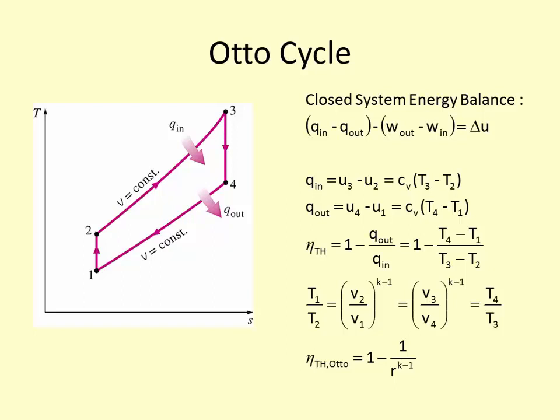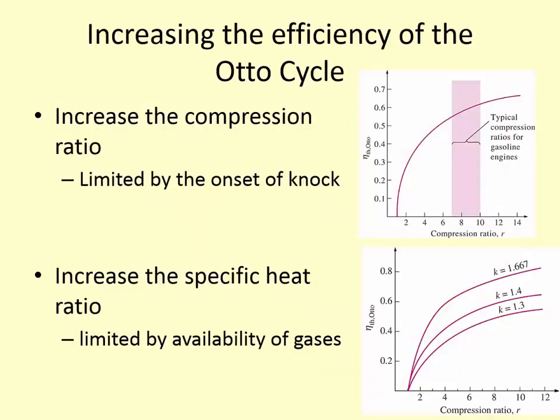Okay, so there are simplifications that we can do that allow us to make analysis again and determine temperature limits or volume ratios or heat addition, heat rejection that will help serve to maximize our work output. Because that's ultimately what we're going for, is to maximize how much work we get out of this system. So we can analyze it that way.